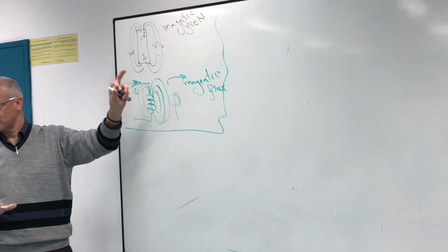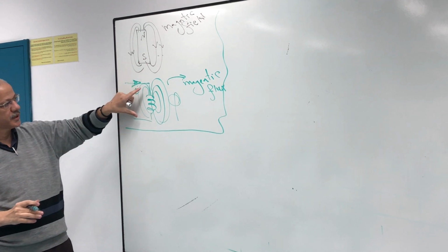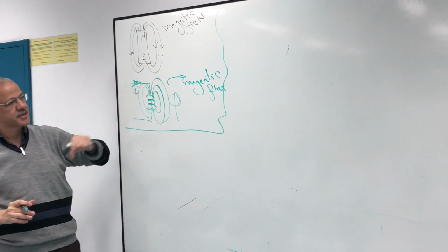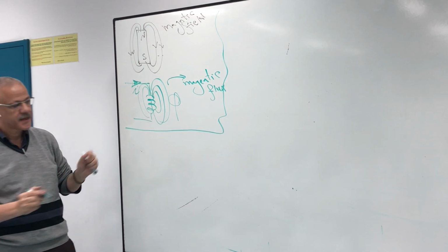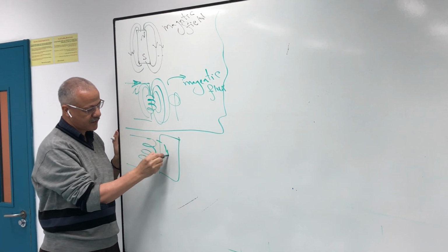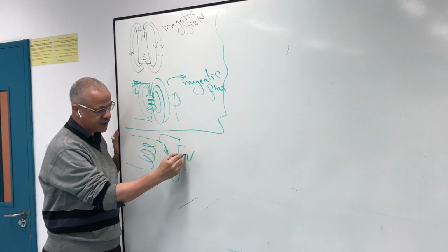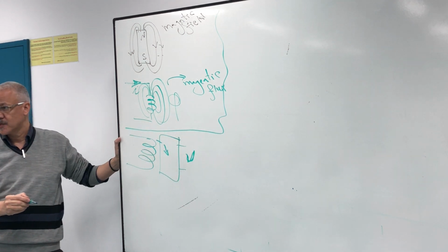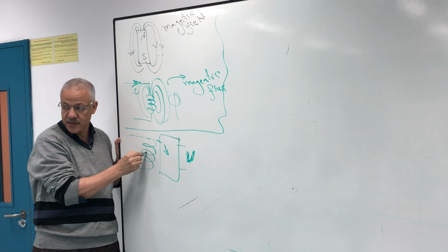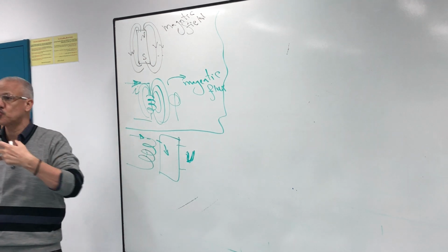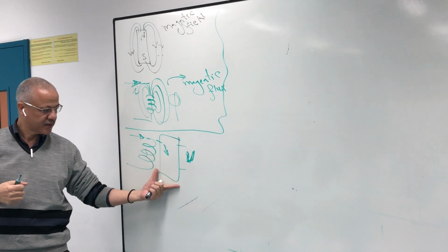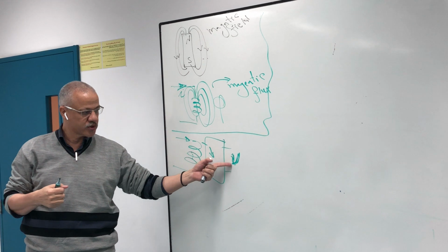For Ampere's law, you have a coil with current injected, so there is magnetic flux. If you put any circuit beside this one, an output voltage will be induced in that circuit due to the flux from the first circuit. Faraday's law means two circuits: a primary circuit and a circuit magnetically coupled to it, producing voltage.